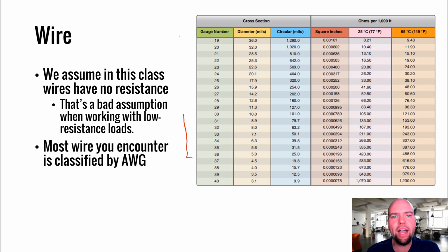things that you'll buy tend to be down to this range. So like HDMI cables, where you have to have 20 to 30 conductors all bundled together in one cord. That's typically where you'll get down into these. These are pretty small wires. So these wires are diameter 8 thousandths of an inch to 5 thousandths of an inch. These are pretty fine diameter wires. They can't carry a lot of current. And they can't carry a lot of current as evidenced by, this is 420 ohms for 1,000-foot stretches.